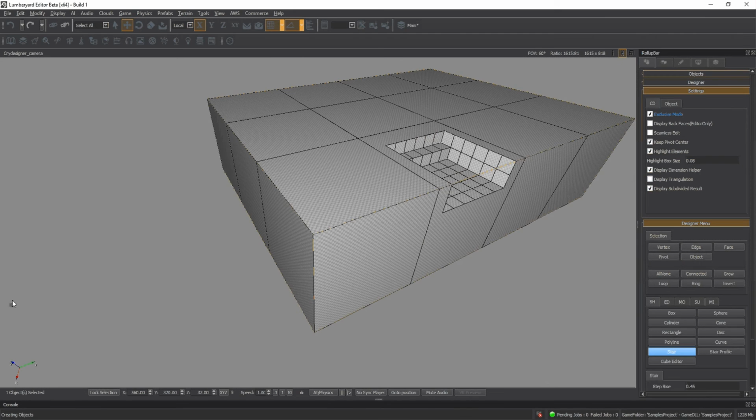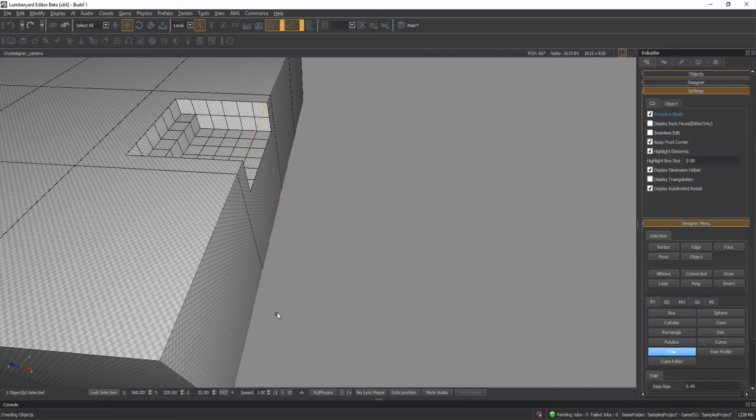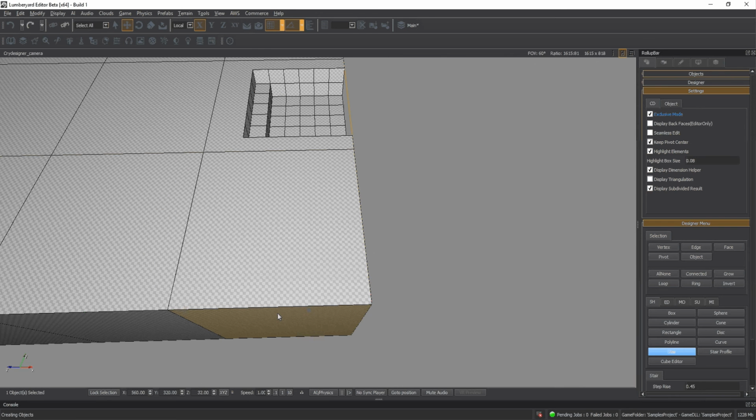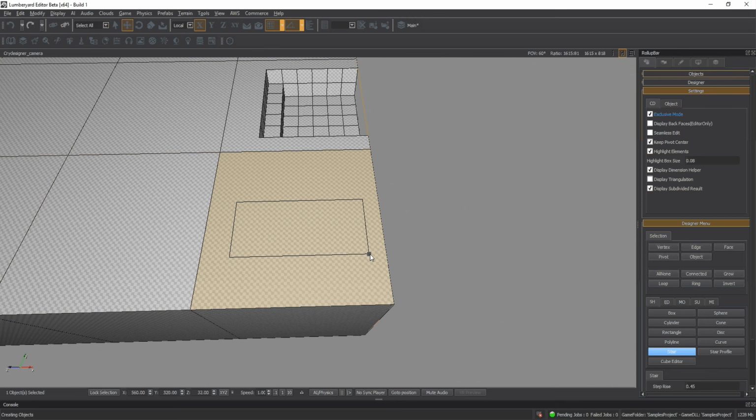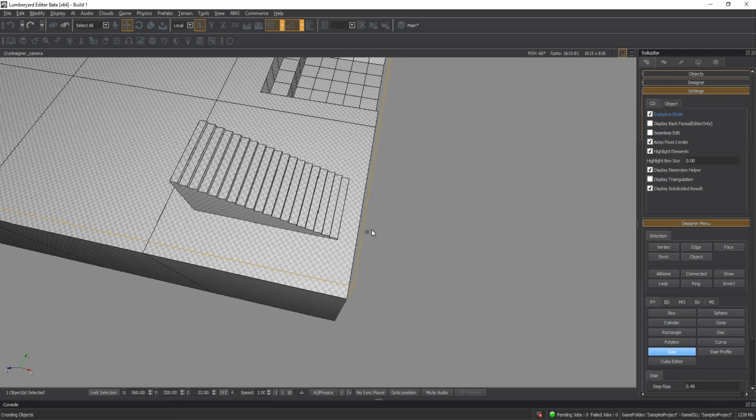Your stair tool allows us to draw along a surface and then add in stairs. Now you are drawing your width and depth first. So how wide you want it, how deep you want the stair to go, and then your elevation in that order.